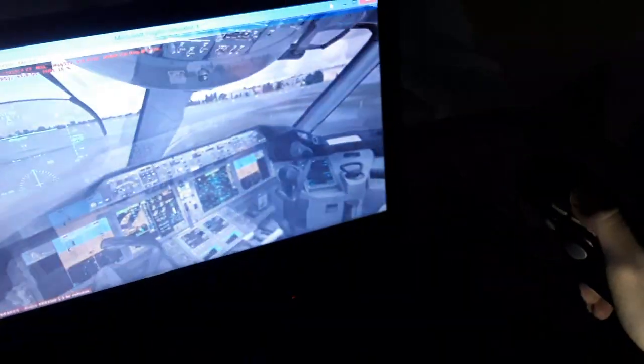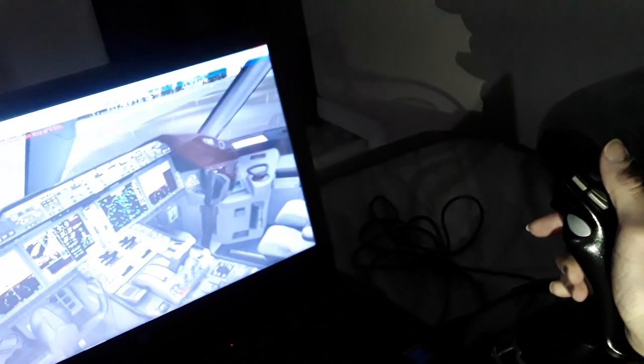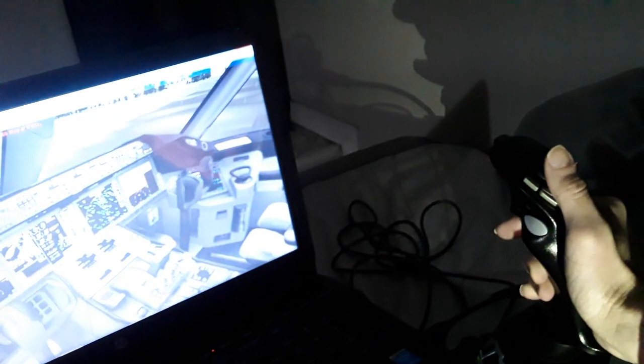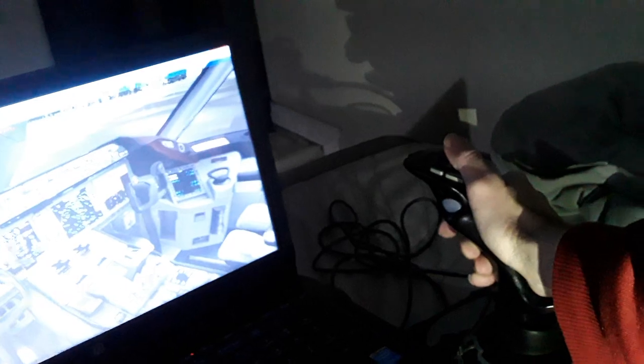In the Airbus we can make left and right turns, limited by the flight control computers in the normal mode, to 2.8 G, where G is the acceleration of Earth gravity. So we have 2.8 G left and right turns, or 67 degrees of side stick deflection with the side stick maintained in the Airbus. Also, we can climb 30 degrees or 1.5 G in the Airbus, or descend with the side stick deflected down, minus 15 degrees or minus half G.